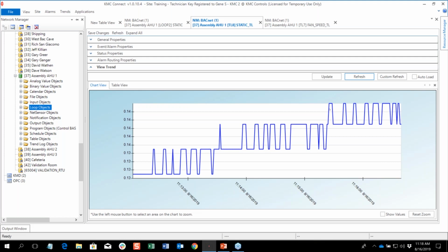It's a little bit of incentive to take your loop output, do some conditioning with Control Basic before you go to the output. If I want to pause it, I can do it there. Maybe that's by writing a value at a higher priority to the variable or to the output. Or if we want to be very fancy, I can write some conditions to look at a BV that say, hey, pause my set point or only update my loops or my output if my loop has changed 10% or 20%, and build some hesitation in that way. But the calculation itself is not something that we would see paused in the real world.